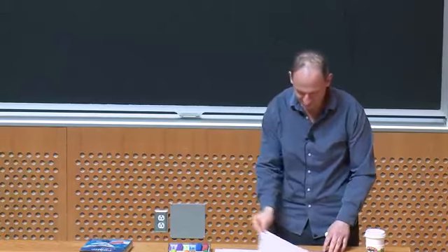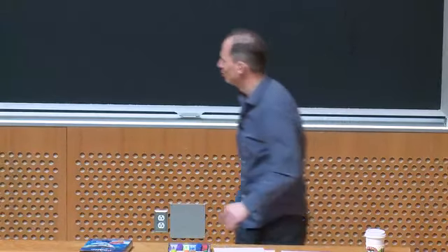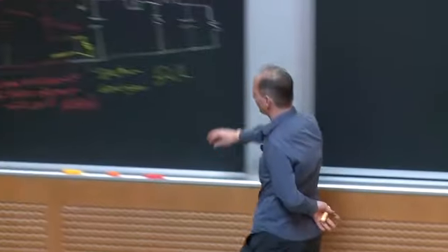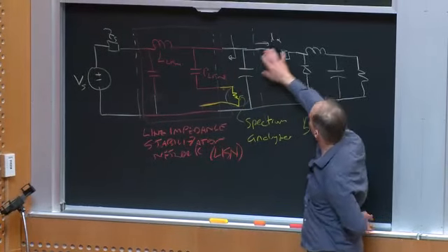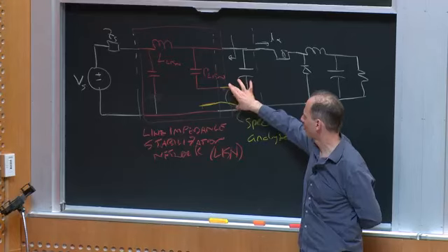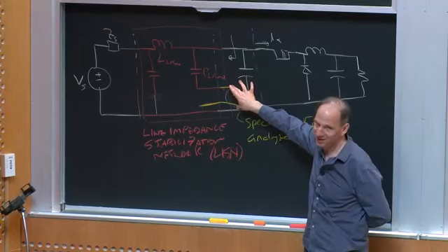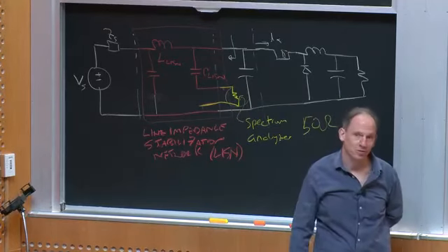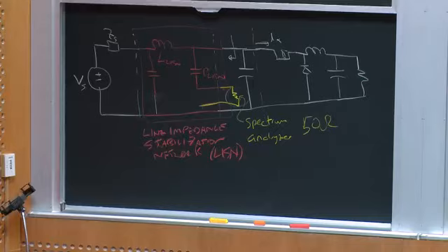So, when I show you, we've got a capacitor here, right? The model for this would then be basically a capacitor in parallel with 50 ohms, and I'm trying to measure that voltage ripple on the 50 ohms. You're going to need more than a capacitor to make this work. Okay? So very often you're going to need a multi-stage filter.